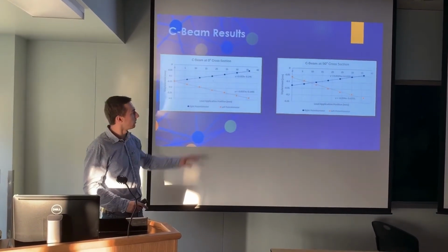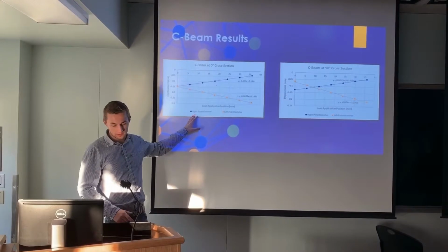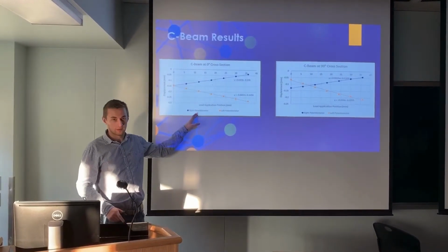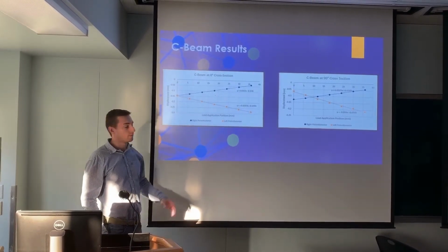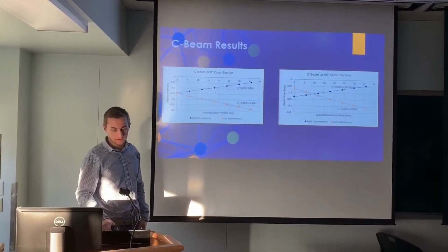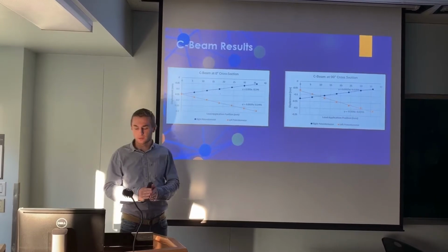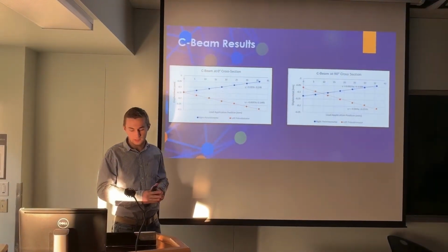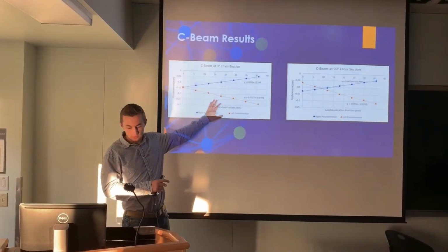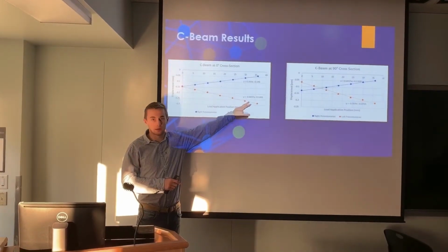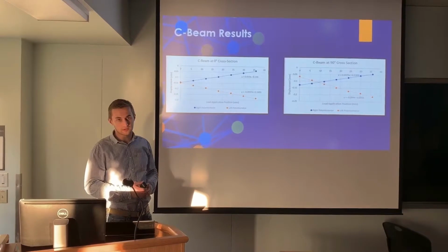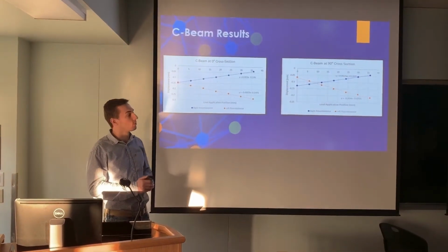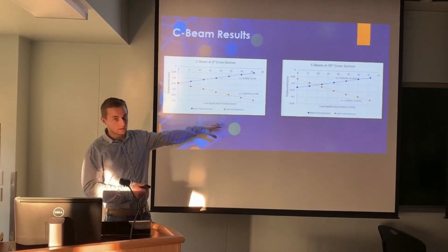As you can see, the one on the left does not clearly show the intersection. This is due to solely changing the position of the applied load towards the left potentiometer. So instead of applying a load at every notch, we only applied it at the left half of the beam cross-section and used the trend line equations to determine where the shear center was located. For the C-beam, it was experimentally determined that the shear center was -0.47 and 9.29.